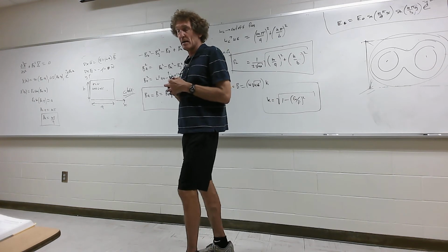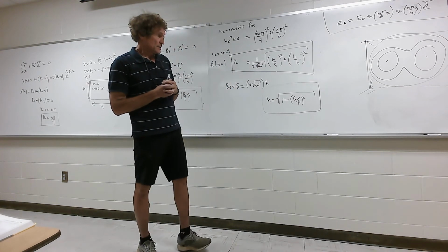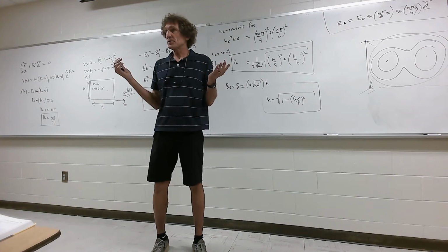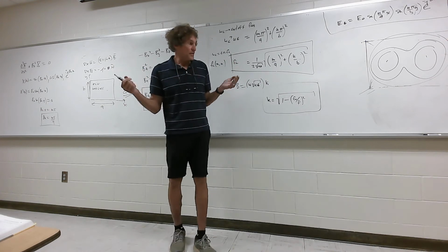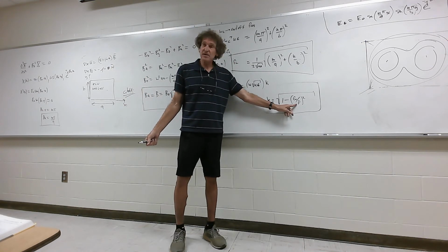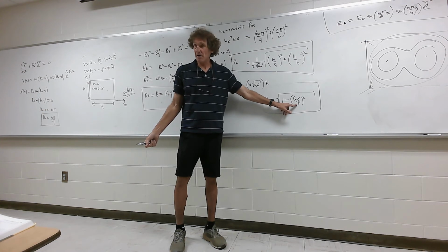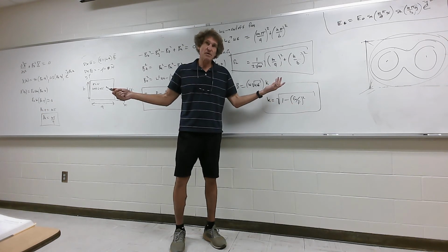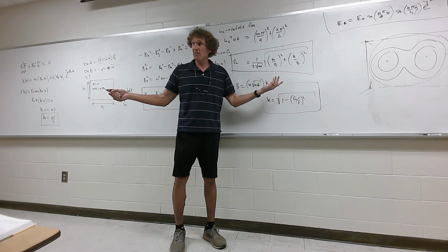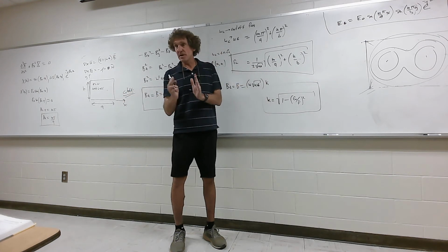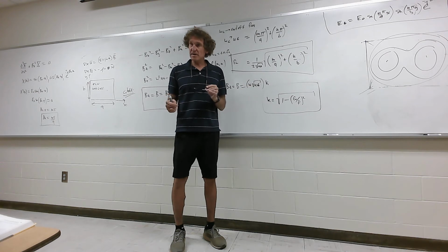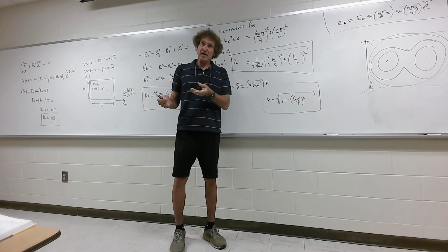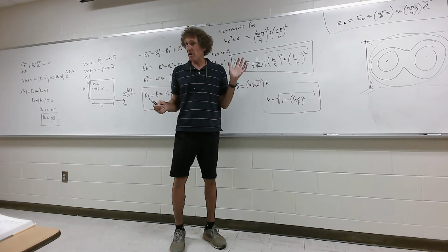I'm still not really sure what K is. It's just a number. It has to do with how close you are to cutoff. When you think about this, if you're at a frequency 500 times cutoff, it's about 1. I mean, 1 minus 1/500 squared is about 1. You all follow me, class? The closer you get to cutoff, the smaller that number gets. And at cutoff it's 0, and that's when nothing propagates.